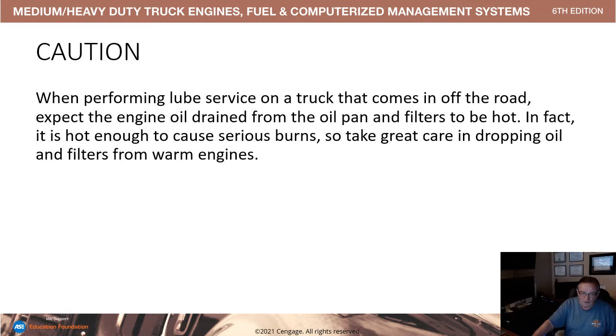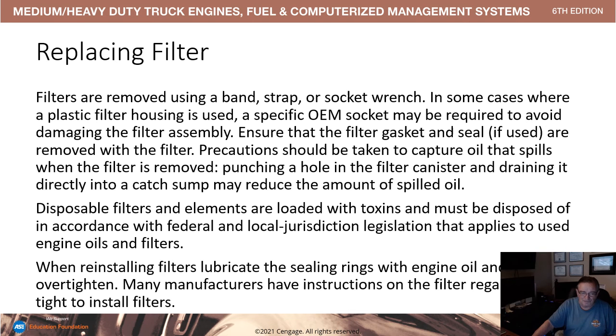When performing lube service on a truck that comes in off the road, expect the engine oil drained from the oil pan and filters to be hot. In fact, it is hot enough to cause serious burns. Take great care in dropping oil and filters from warm engines.